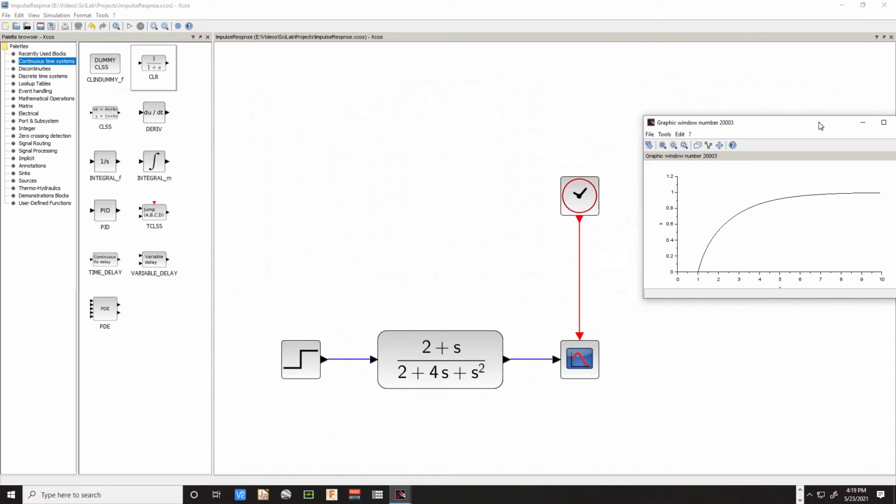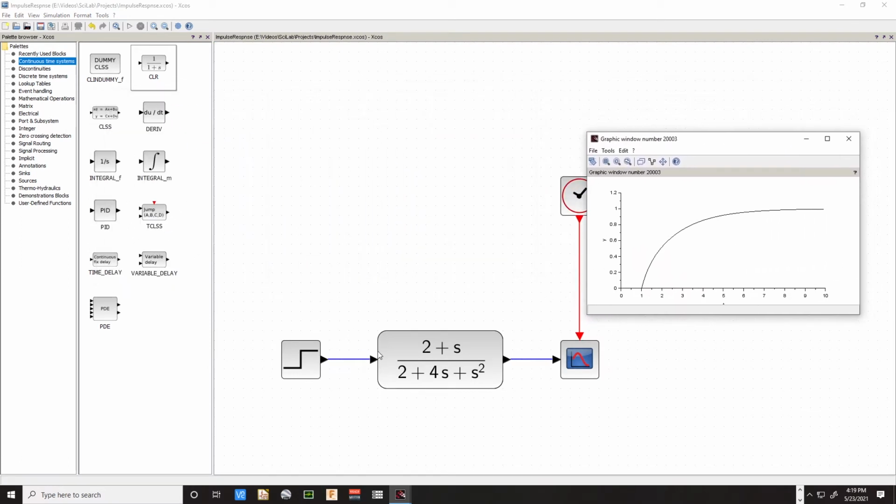So this graph is the unit step response of this transfer function with respect to time. So this responds to time in this manner, and it slowly approaches near 1. Okay, a couple of things you'll notice about it. If we come up here to about 66% or 63%, and we come straight across, oh, this should be 50% should be. Oh, that's a different equation. No, never mind about that.